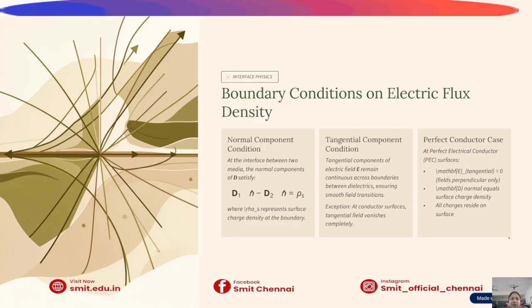Next, the tangential component and the perfect conductor case. Another important boundary condition applies to the tangential component of the electric field intensity E. At the interface between two dielectric materials, the tangential components of the electric field remain continuous, ensuring smooth transition of field lines across the boundary.